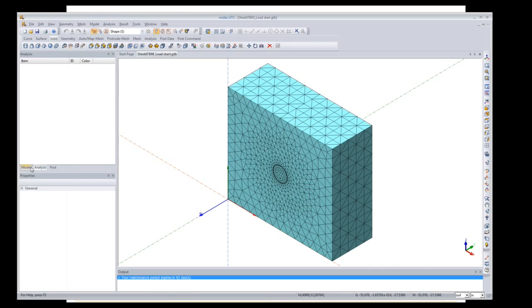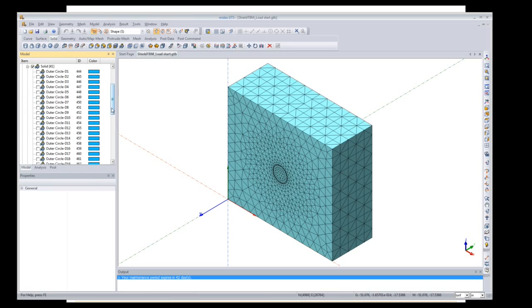So what I'll do is just quickly start defining the loads. So we'll select the inner circles or the inner solids. And another important thing to be noted here is that we have already meshed these solids and we are applying these loads onto these solids, because when you are running the analysis, the program automatically converts the loads that are applied to the geometry, we call solids as geometry, to the mesh sets automatically. So again, this will make your modeling process much easier, which other software are not able to do.